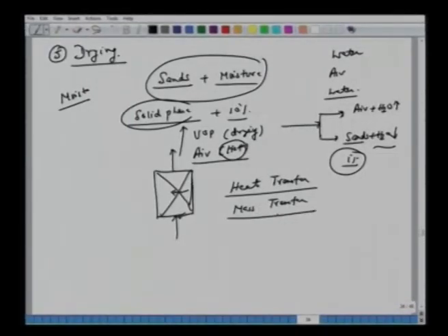In the previous unit operations, or the examples which we had, say absorption, extraction, all right, or adsorption, they can also be accompanied by certain release of heat or gain of heat, loss of heat. But generally for this course, we are saying that this process is more or less isothermal. That means the amount of heat released plus or minus, exothermic or endothermic, is negligible.